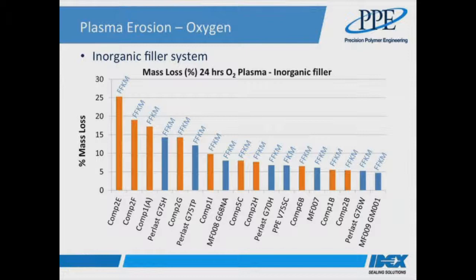And again, it looks like there is actually an FKM which shows fairly reasonable performance and able to mix it with the better performing FFKM materials. So we can conclude that it's not necessarily the case that all FKMs with inorganic filler are going to be worse than FFKMs with similar filler systems.